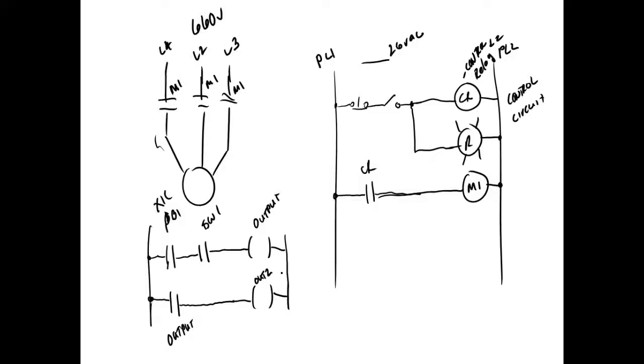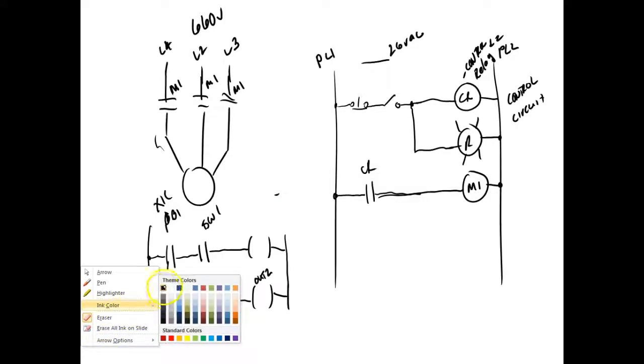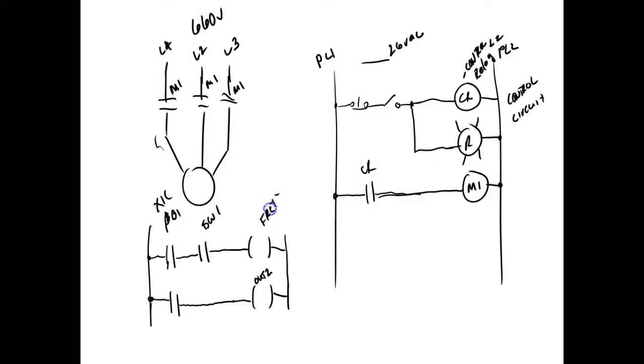I agree with you, but I'm drawing it up here, and I can call them anything I want to. I'm making a demonstration. All we've got to do is understand that if I call this an output, then any contact that's controlled by that, I'm going to give it the same name. So I could have come up here and called this Fred, and then down here I could label this contact Fred, and that means that contact is controlled by that relay. So all we're doing is just trying to demonstrate how. Okay. Are we okay? And like I said, I'm not going to keep switching over to the print.